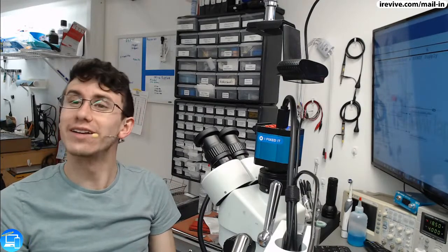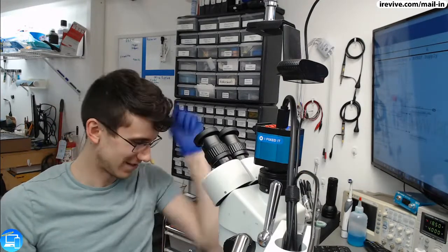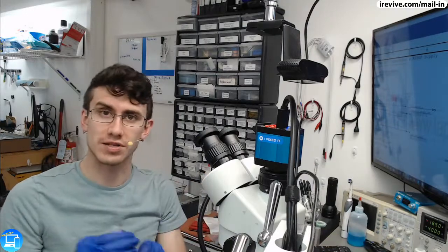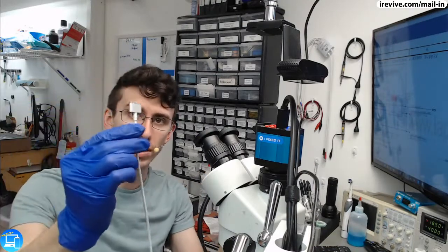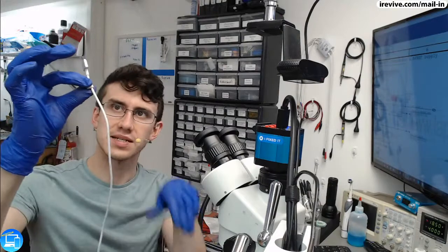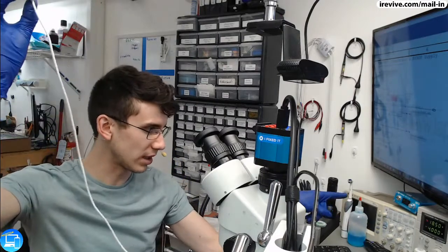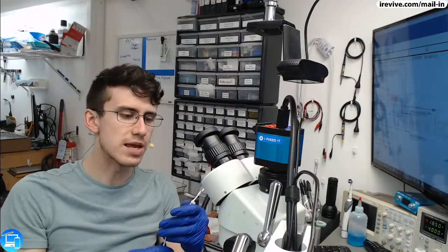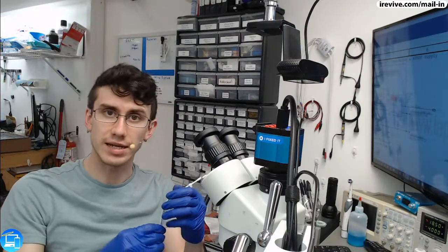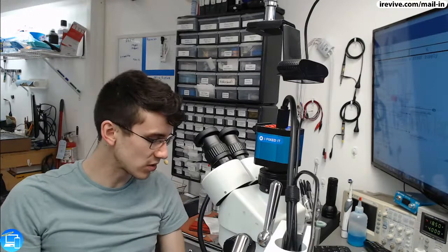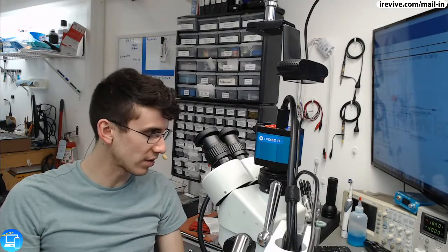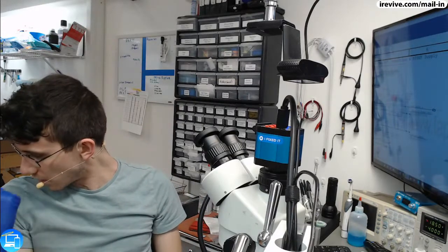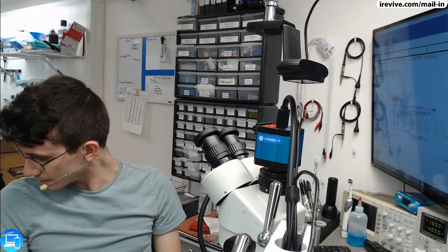Did you say it's powering on? Yes. Triggered? Indeed. Alright, so if you use a power supply, I recommend using an OEM Apple charger, just slicing off the tip of it and plugging the outer metal shielding to ground and the inner insulated cable to power. That tends to resolve our issue here because our issue ultimately was our charger. You know, come to think of it, we actually had a client.